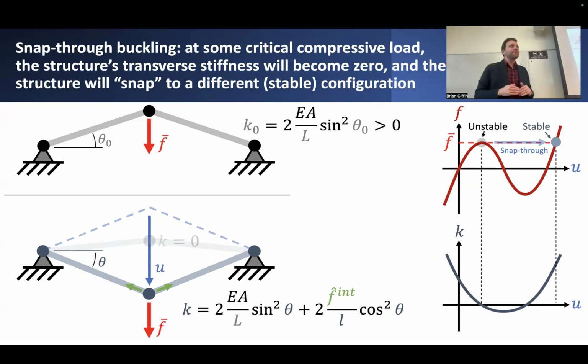You apply some load, and at some critical load, you determine that there's an instability that converts the structure from one initial configuration to this deformed, or snapped through, configuration. It's kind of like those little rubber toys, those caps that you can invert, place on a table, and then they snap through and pop up off the table. Kind of a fun experiment. If you can find one of those, go ahead, try it out. You'll witness snap through buckling in action.